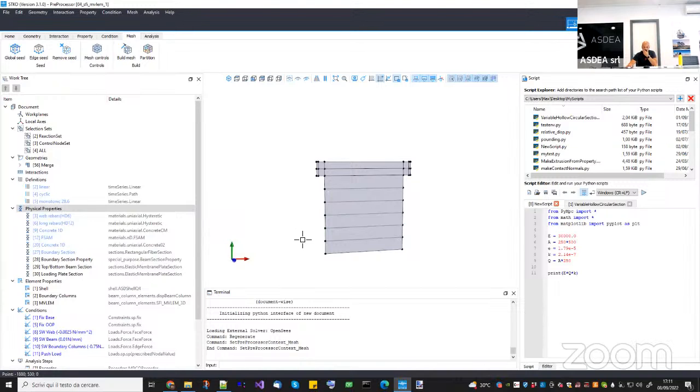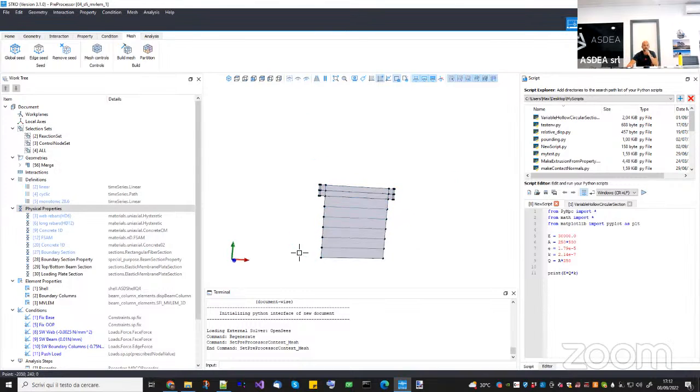And then there is another problem. Whenever you try to model strain softening, so you have problems like when you have concrete or masonry, whenever you have a material that shows degrading response, it is very problematic to model this with finite elements. You have a lot of problems. So I've been talking about the concept of fracture energy regularization, which is a sort of first attempt to regularize the response, but also that one is not perfect. So the first rule is that you have to pay a lot of attention. You cannot just think that one model can work right away, okay?